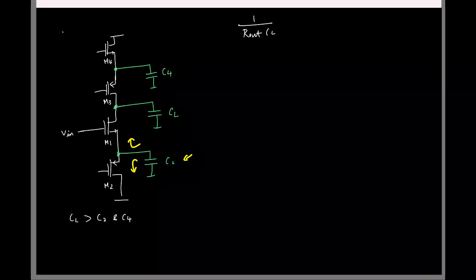Again, I found some of you had actually opened all the capacitors, and to find the looking-up impedance, you included the cascode of the entire thing. That's not correct, right? Simply because now we are looking at the non-dominant pole, and the assumption is the poles are very far apart. So the non-dominant pole is at a much higher frequency than your dominant pole. So by the time you encounter the non-dominant pole, the capacitor that contributes to the dominant pole will behave like a short. So this is now a short circuit for all practical purposes. You cannot say anything about C4, but one thing you can say for sure is CL is short.